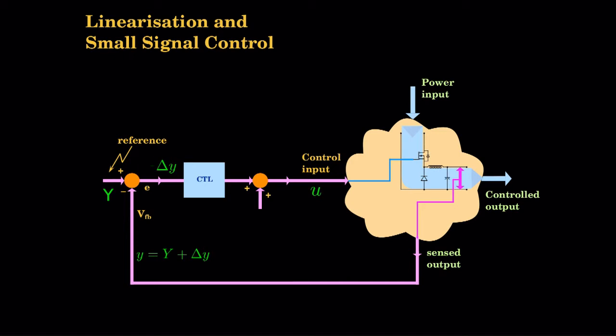The DC motor is a linear system where the back EMF EB is K times omega, K is a constant fixed, and the torque produced is K times IA, again K. So, you see that it is a linear system from 0 to some operating point. Maybe beyond that, if you go, saturations and other non-linearity issues may set in. But in a region where it is defined 0 to some max U max or X max, it is linear.